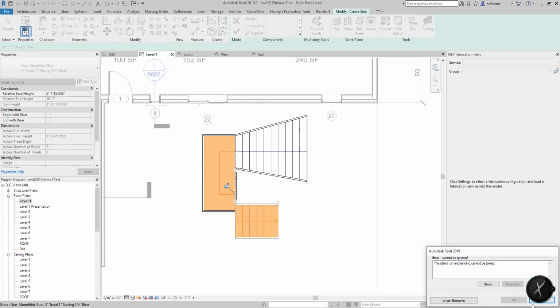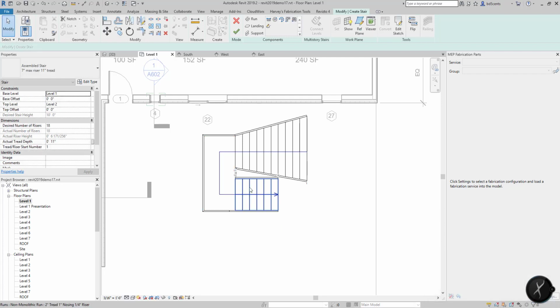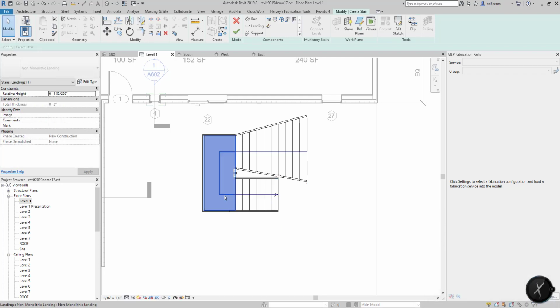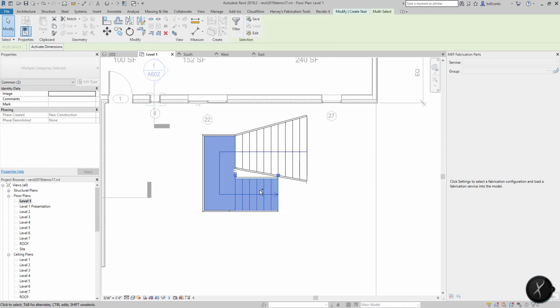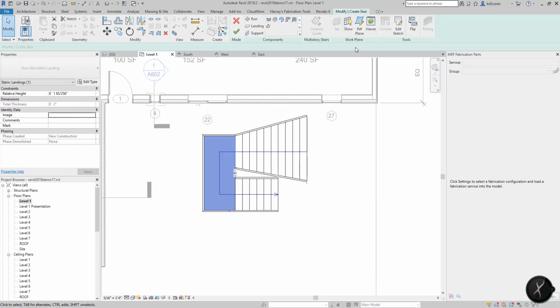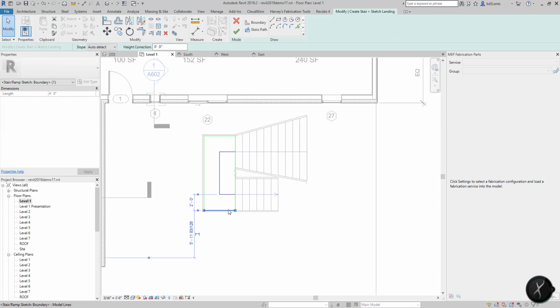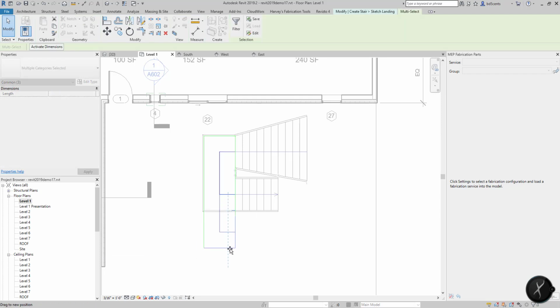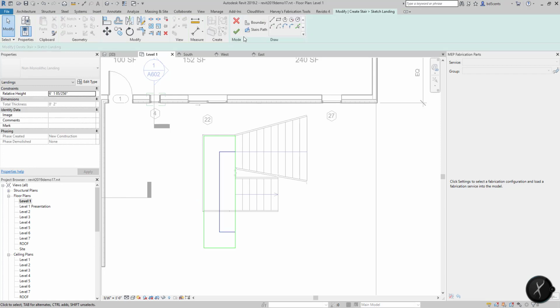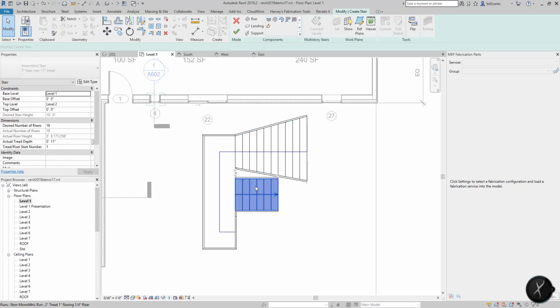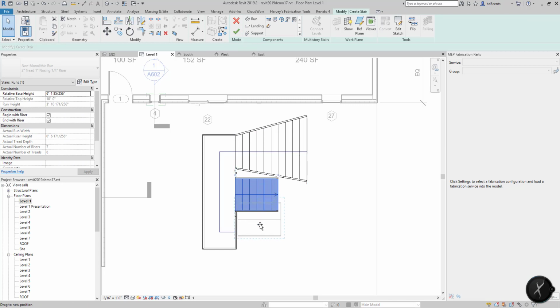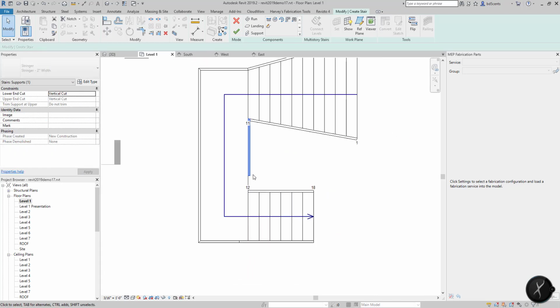Now, one thing to note is that because we've converted it to sketch, it's not going to pull this as well. So we would actually have to edit both sketches. So I'm going to edit this sketch first, and I'm going to pull this value down to where I want it to be. And then I'm going to hit finish, and I'm going to move this value down to the end. And you'll notice that it updated.